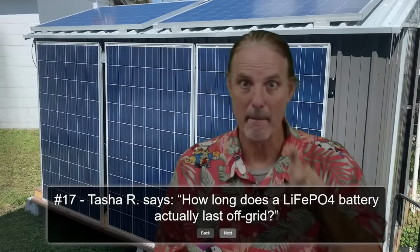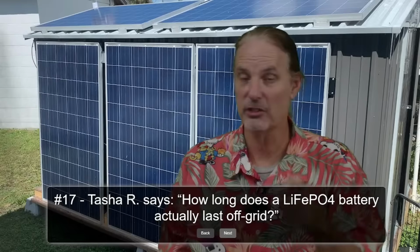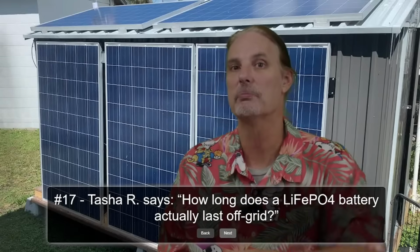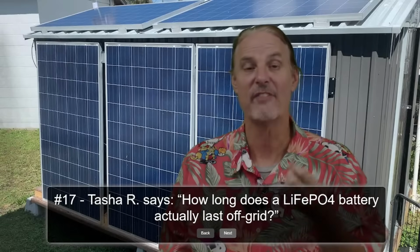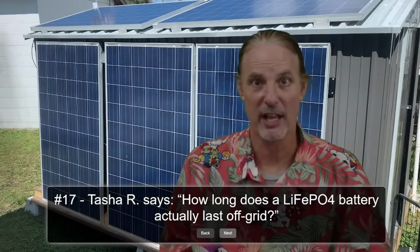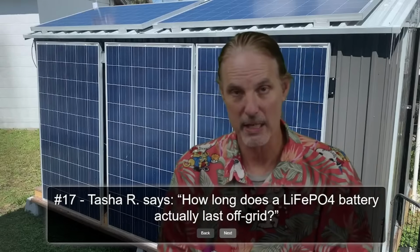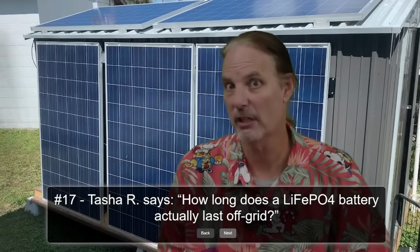Over time, the battery is going to lose some of its capacity. In the case of a JK BMS, or in the case of the EG4, the EG4 has a lifetime cycles meter that calculates what they call the state of health. The state of health means that if I'm at 95% state of health, my 100 amp hour battery is now a 95 amp hour battery. In the JK BMS, you can go in and adjust the size of the capacity of those cells.